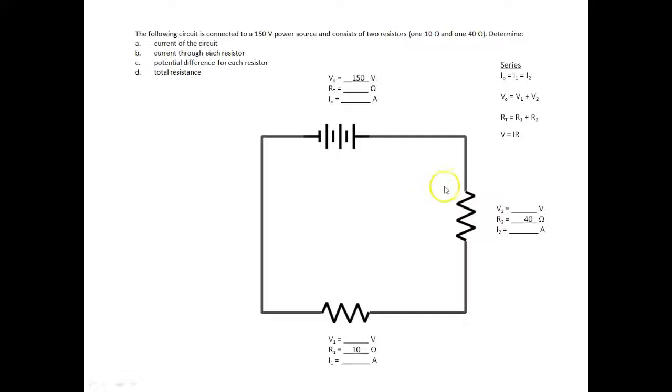And finally, because of the manipulation of the equation V equals IR, we know that my total resistance is equal to the sum of the resistance of each of them. Again, this is just Ohm's law. So the first thing we can calculate is our total resistance. Since we don't know our initial current, knowing the total resistance will allow us to determine that. It's just equal to the sum of the resistance of the two loads that are in series with each other.